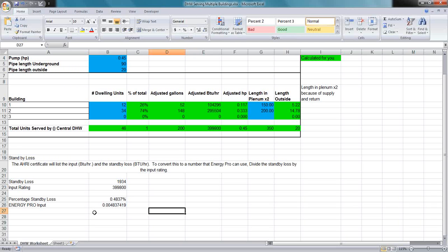This is another question that speaks more to non-residential larger systems where the pump power can really balloon. So it depends on what you're using it for. If we're talking just little recirc Grundfos pumps that you typically see in the buildings, feel free to use professional judgment or give us a call and we can work it out with you on what the brake horsepower should be for that system.